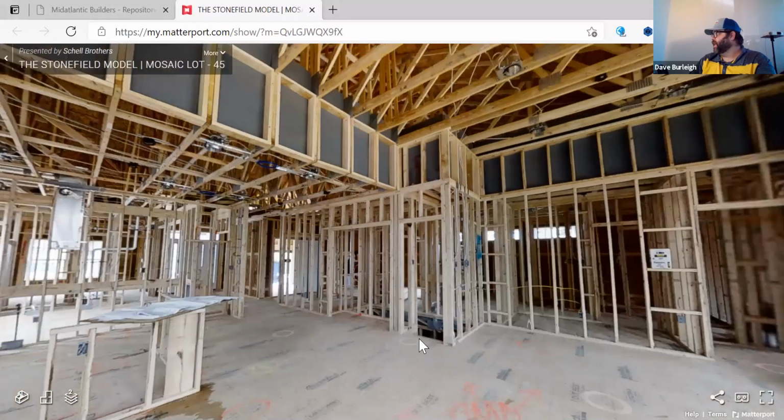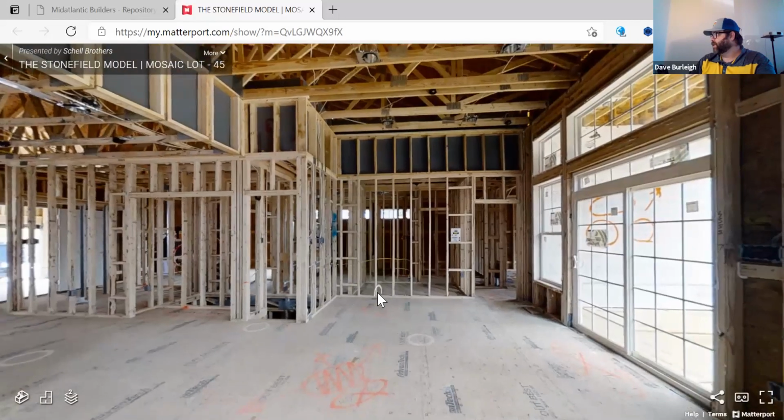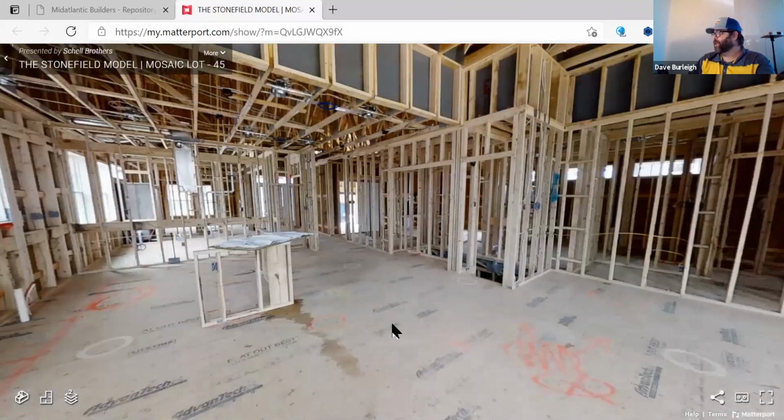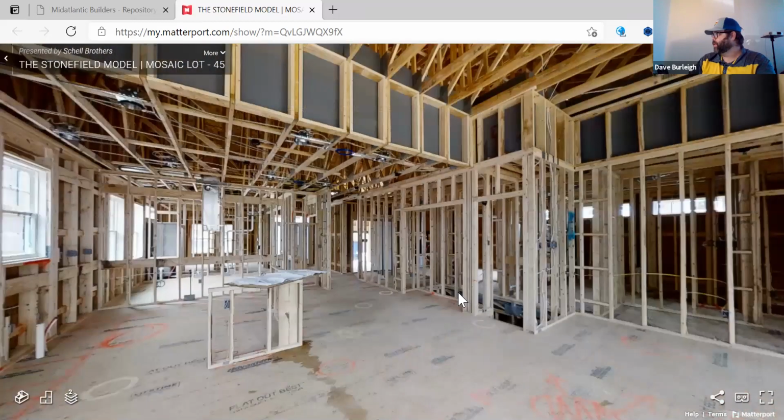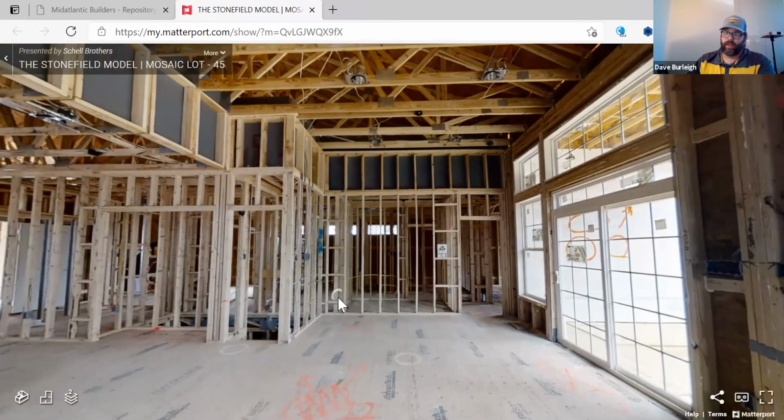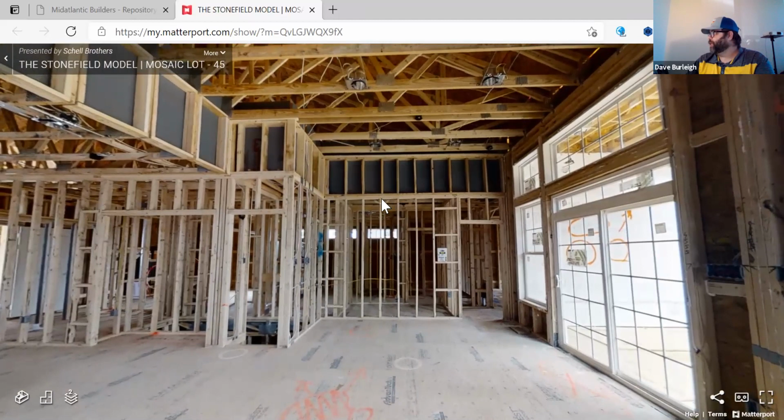And where details really matter is this is where when we open this, it opens right here. All I have to do is turn 90 degrees to the right. And we ran into our first situation where what was built does not match what was designed and what was purchased. Because we were able to quickly see that instead of doing a full height wall to the bottom of the trusses in this volume area, we actually piggybacked a pony wall on top of a regular wall.